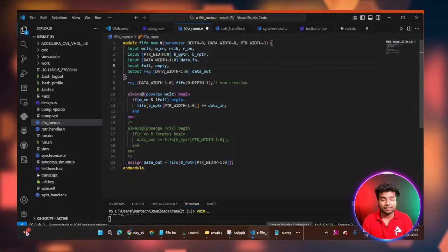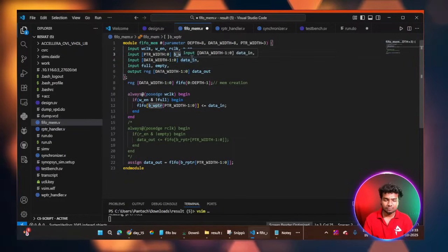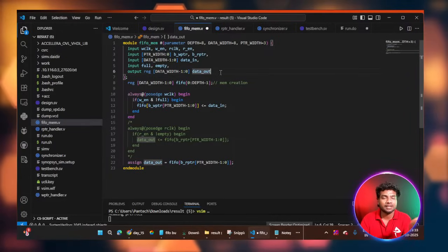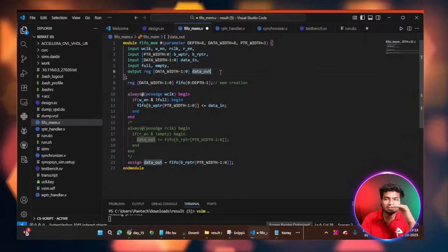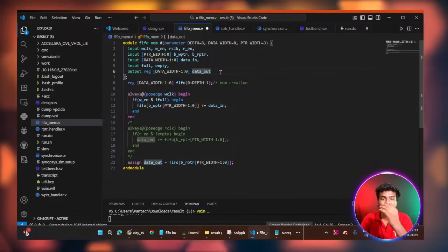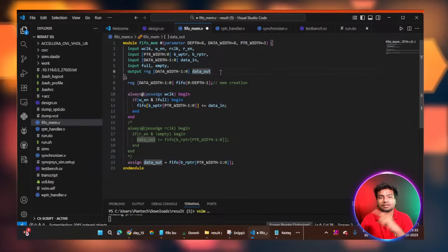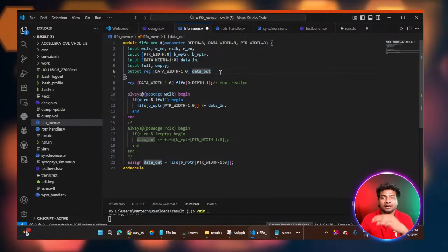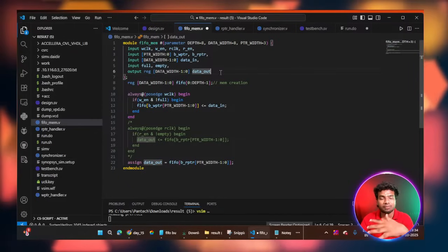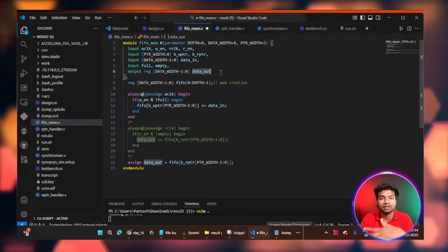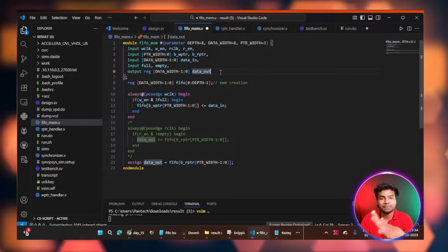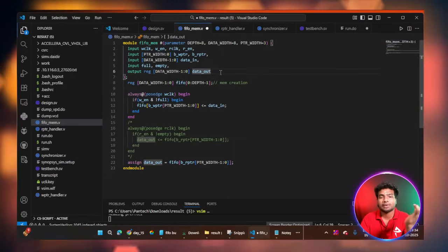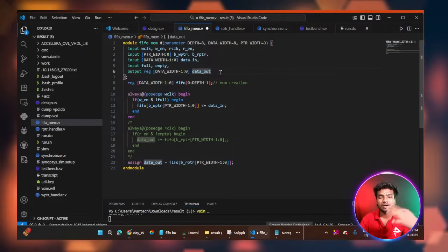Firstly I'm having the pointers like addresses. A pointer tells the address of a memory location; it points to the memory location. Firstly I am creating the pointer in binary, using the binary sequence, and then I'm converting it into gray. But what I'm actually going to use is the gray coded pointer only.